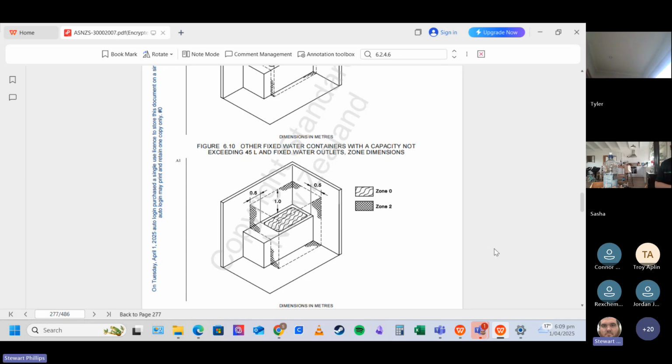But yeah, if you're doing solar installs and you've got to put a switchboard somewhere, I would be more inclined to, if the switchboard's old and you can't just add to the switchboard or you have to keep it separate, I would be inclined to put a switchboard outside, an IP rated switchboard, rather than me in the laundry. But that's just my preference. I avoid laundries other than just one single PowerPoint.